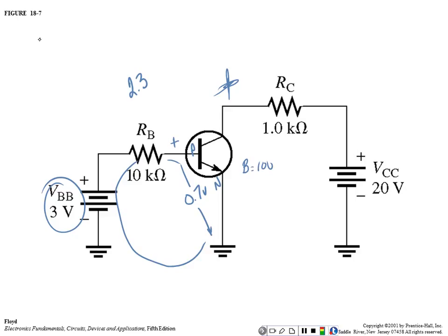So this is my circuit right here, and we've done this several times this term, right? I got a 3 volt supply, a resistor right here, and a diode that is forward biased. How many times have y'all calculated this and screwed up on the test? We've got two tests coming, and I guarantee you, it's forward bias. So if it's forward bias, this guy right here drops about 7/10 of a volt. Kirchhoff's voltage law says the sum of the voltages has to equal the applied voltage, right? So what's it going to drop? Well, that means this guy right here's got to drop what?